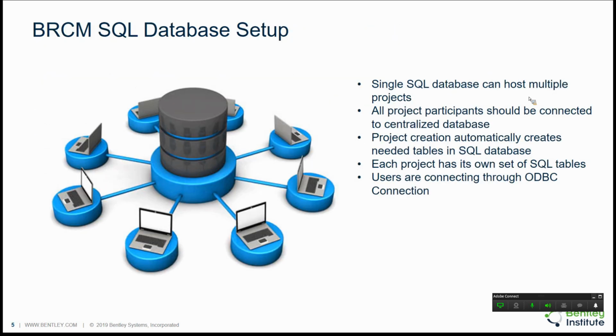So Bentley Raceway and cable management is utilizing an SQL database. By default, we ship Bentley Raceway and cable management with an SQL Express database. And there are several variations for how you can set it up. The single database can host all your projects. We have users that use a single database for the entire organization, or users that have a separate database for each site. So it's all up to you.